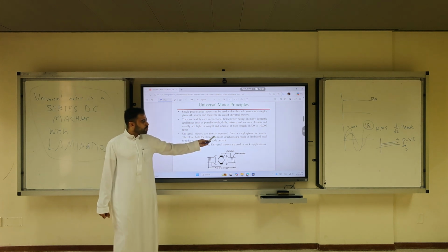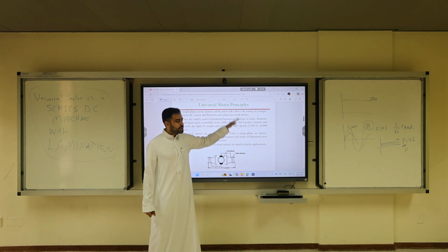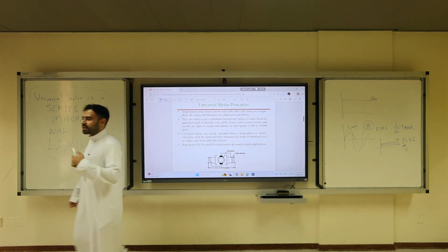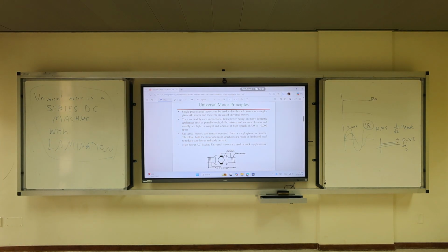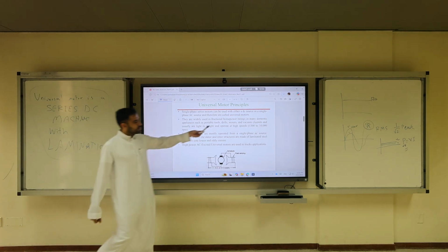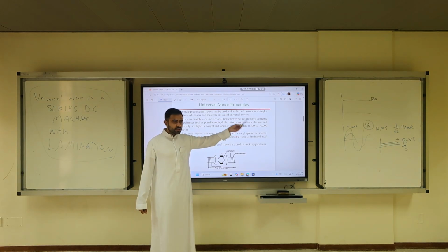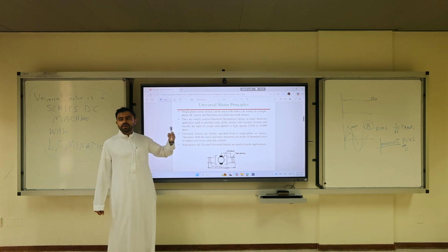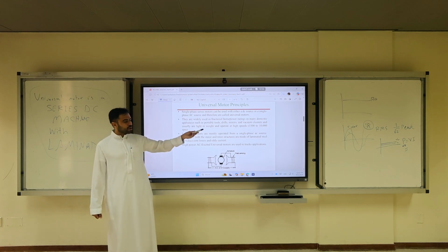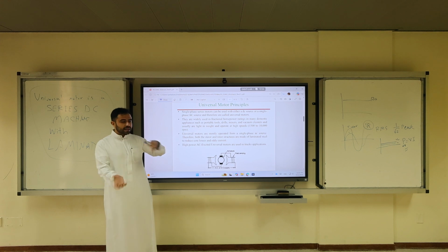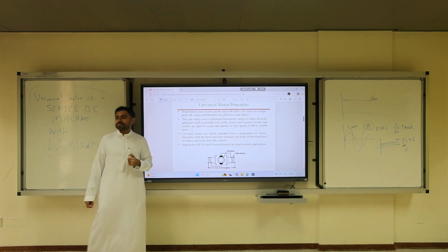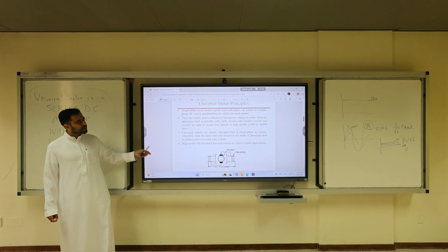Okay? So if you want to do it in AC, does it make sense to have it 3-phase or single phase? Single phase. Why? Because we only have access to single phase as customers. Can I sell a mixer and tell the user you should have 3-phase power? That doesn't make sense. Vacuum cleaner? No. It has to be single phase. So it should include some small power electronics, not the expensive ones, and it should adapt. DC machines are also cheap to manufacture, similar to induction.